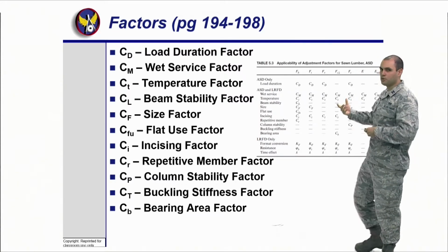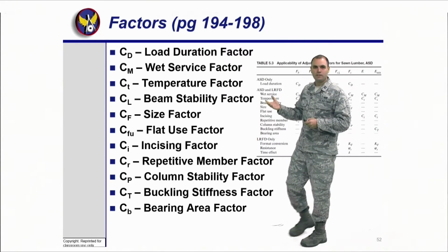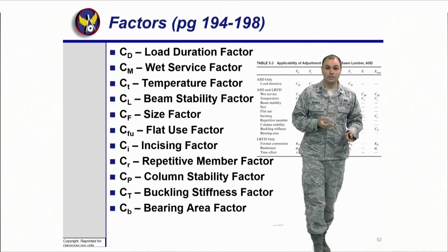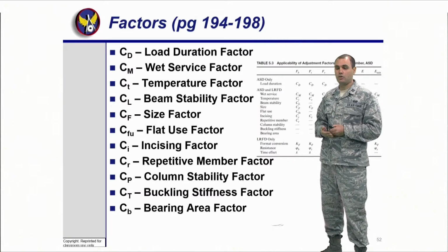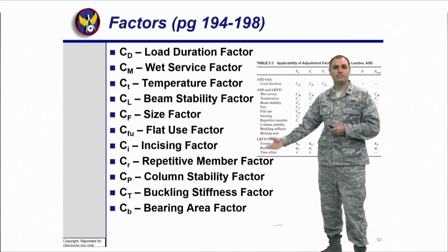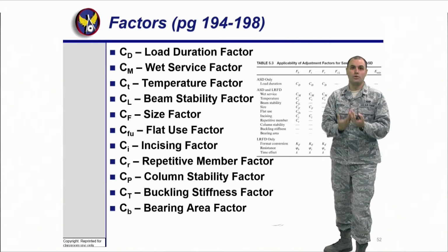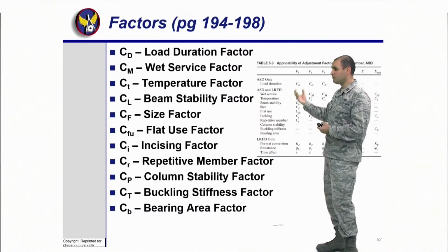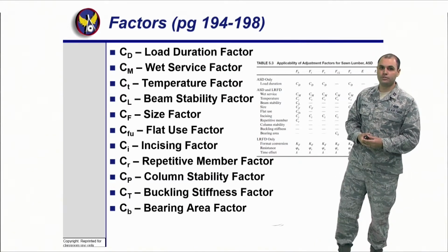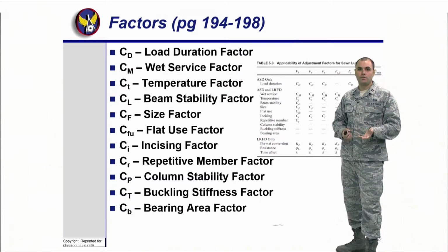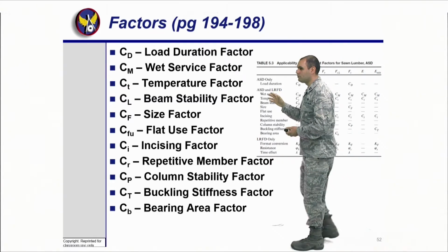Other thing, factors. You're going to see this table in your book. I'm going to go a little bit over it also, but where am I putting it? Is it going to be a wet location or a dry location? Is it going to be freezing or is it going to be warm? All this stuff actually affects it. And all these factors, obviously, you only select the ones that are applicable to your use. You use correction factors that can either increase or decrease your load for your design. So don't get scared because you see so many factors.